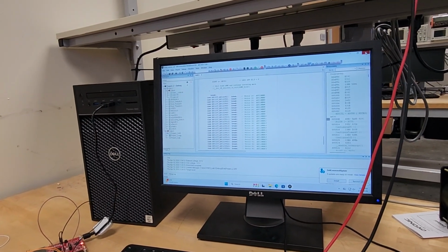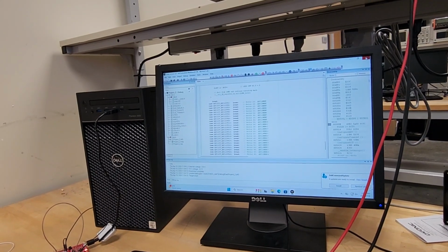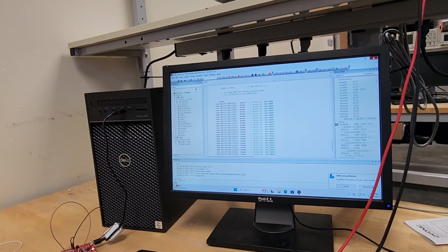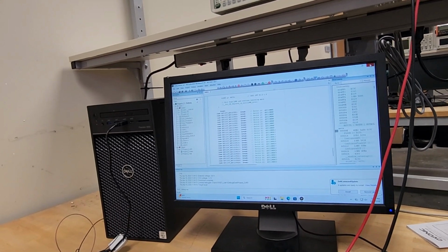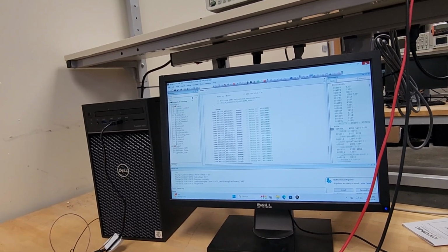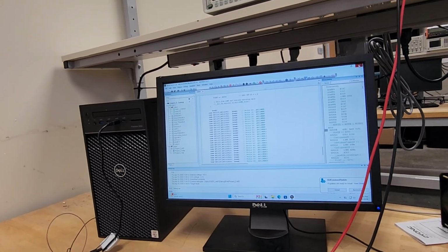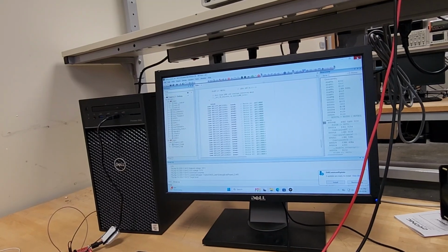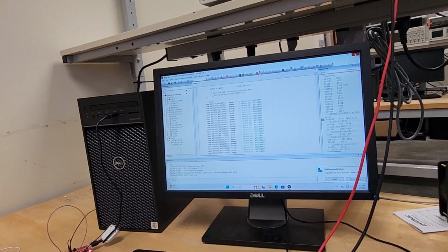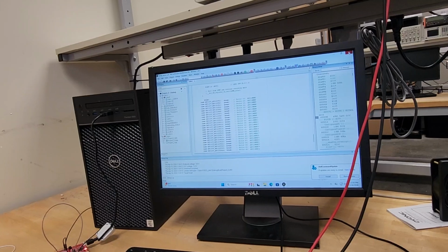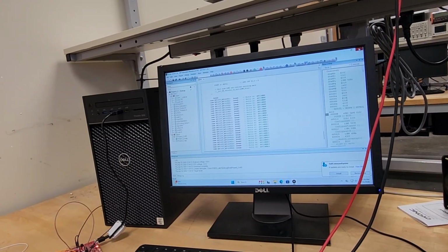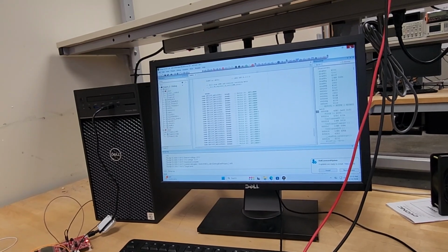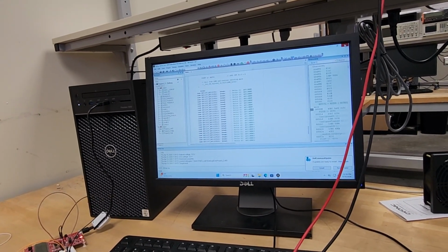The ADC converts the analog divider voltage into a 12-bit digital value. Inside the ADC interrupt, the program converts this digital value back to the actual voltage using the known ADC step size. From that, the code calculates the thermistor's resistance using the voltage divider formula, and once the resistance is known, the program applies the beta form of the Steinhart equation. This produces the temperature in Kelvin, which is then converted to Celsius.